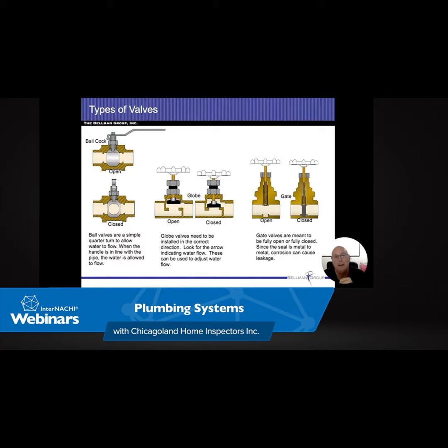So as we look at this picture here, we can see the toilet on the right, and we have our slope going down and away. That's our soil pipe. The sink that's on there as well, that ties into our soil pipe. And then if you see the stack that goes up, that stack keeps going up and down so that it lets water and air.